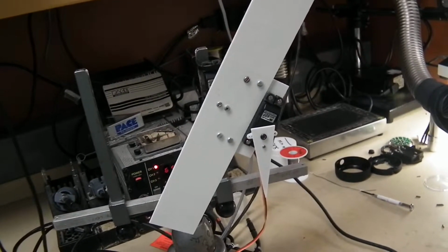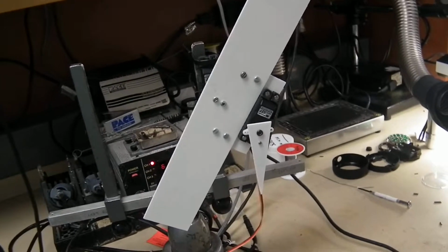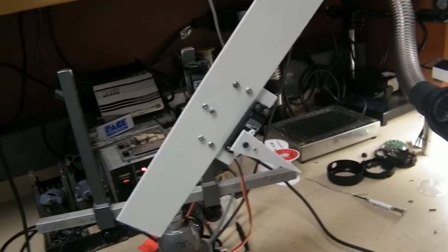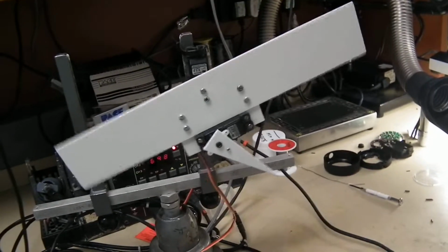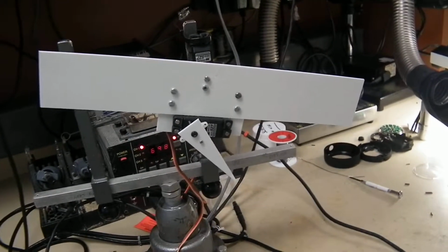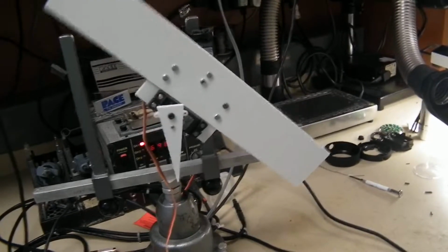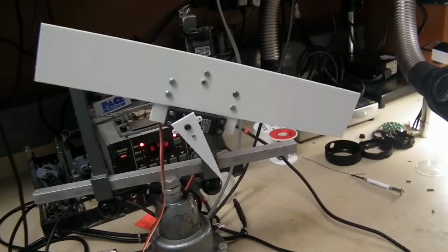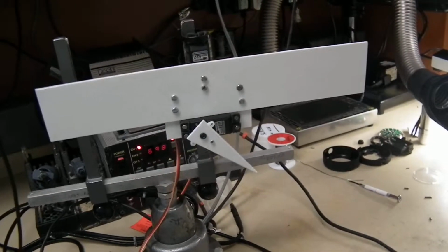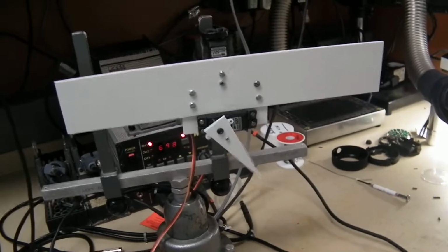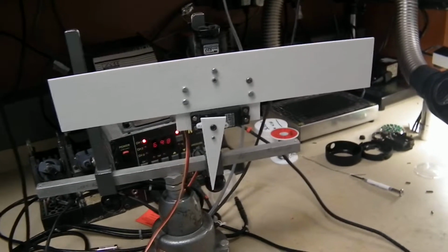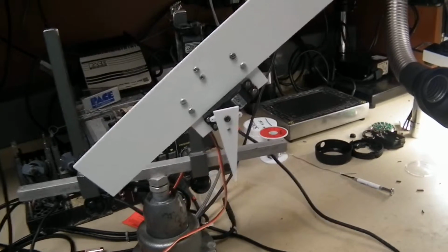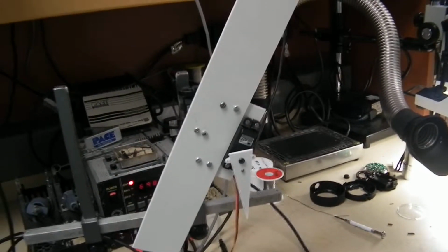And if we bring the actual camera up to perpendicular and demonstrate it in the opposite way, you can see now that the platform behaves in the same manner. I've overcome this problem with the wraparound effect by just a simple correction to the formula to generate the differential angle. I've now sort of fixed that problem.